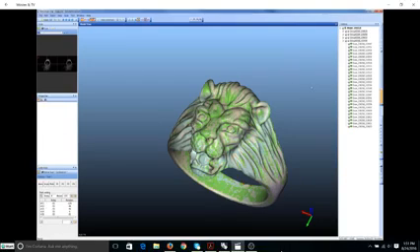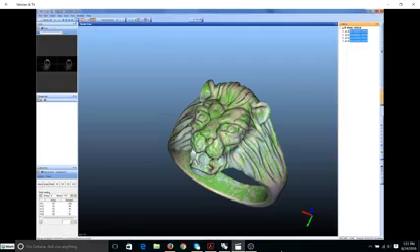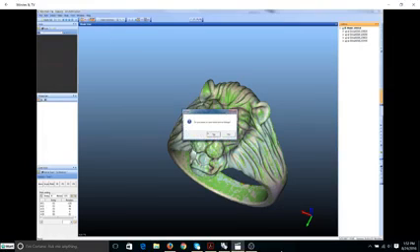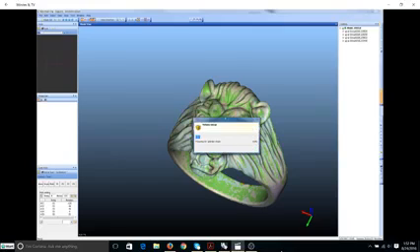Once you do that, you can't go back and edit, so the software is going to prompt me, in this case, do I want to save this before I commit to this? So I do that. I usually make a separate file just in case there are any problems, so I don't lose my original scan data. Now we're highlighted here on our model group in our stack, and I'm going to go right here and say Tool, and we're going to do a volume merge. We'll do this at a high degree of accuracy, which is 0.06, so about half a tenth of a millimeter, basically a couple of thousandths of an inch. No, we don't want to save it right now.